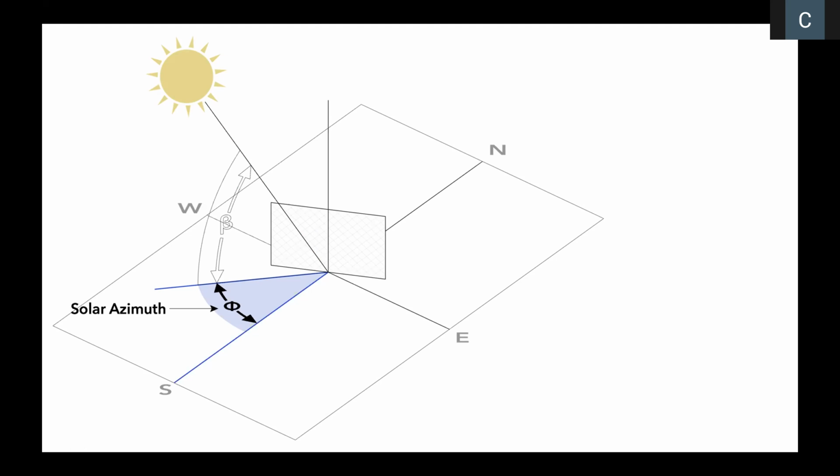It's important to note that when you're saying an azimuth or writing an azimuth in the exam, you always have to say east or west of south. Let's imagine this is a 30-degree west of south azimuth that's indicated here on this graphic. If you just say 30 degrees on your exam answer, it is unclear if you are talking about this angle or this other one here, which is also 30 degrees measured from south, but going in a different direction. So be sure to specify the direction from south of an azimuth angle.